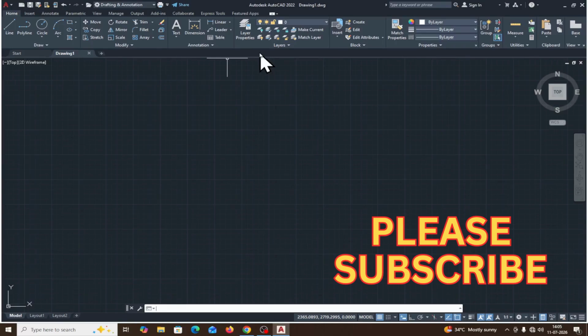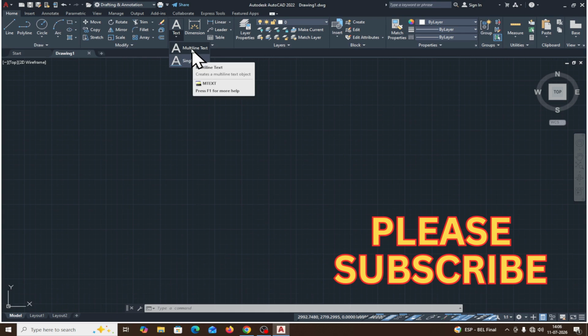Hello everyone, in this exercise of AutoCAD we will understand how to write the single text. In the annotation panel in the ribbon bar, here you find the text. There are two types of text, single line text and multi-line text. I will discuss only the single line text.